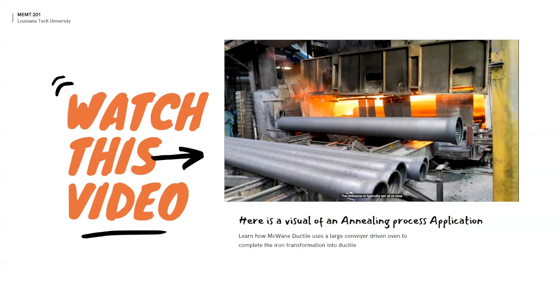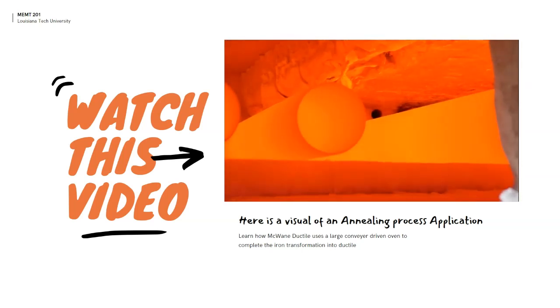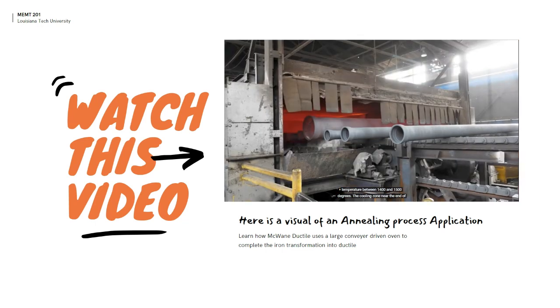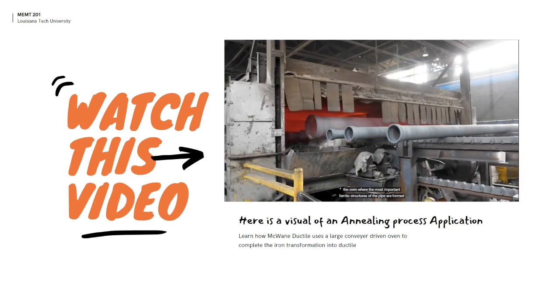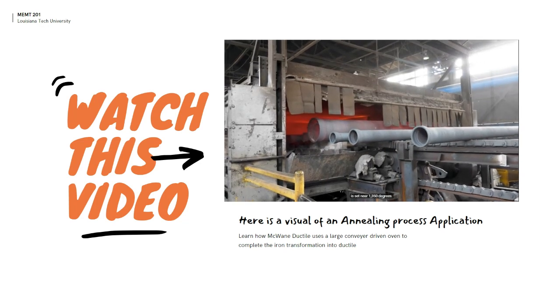The entrance is typically set at or near 1,800 degrees. Primary zones in the middle of the oven maintain a temperature between 1,400 and 1,500 degrees. The cooling zone near the end of the oven, where the most important ferritic structures of the pipe are formed, is set near 1,350 degrees.